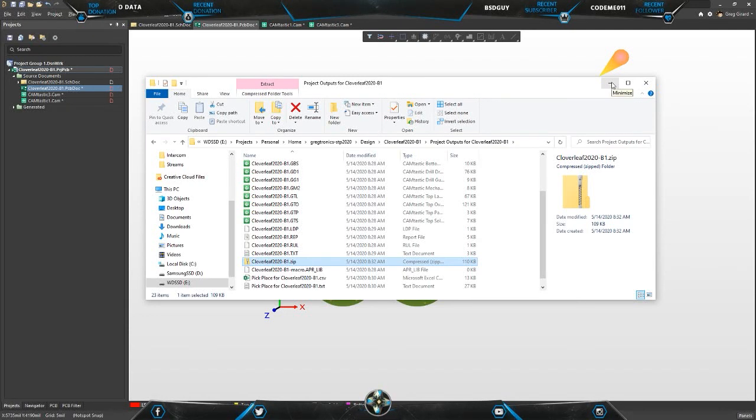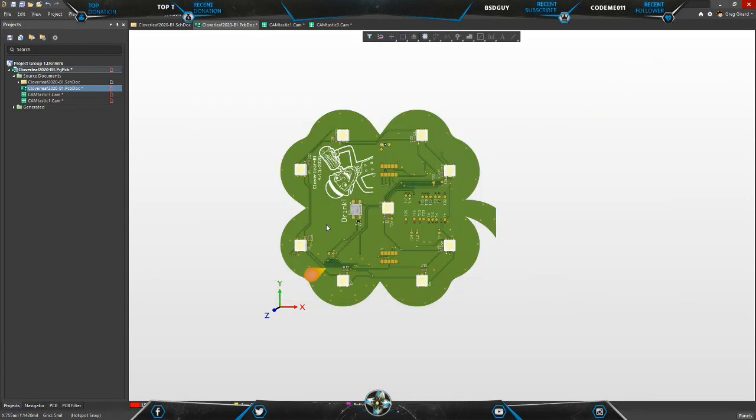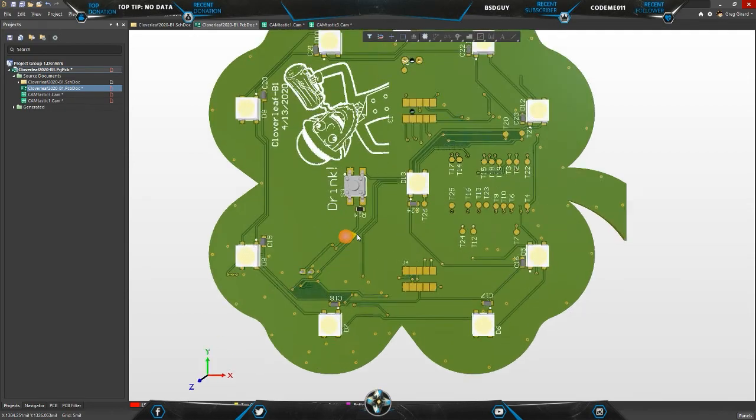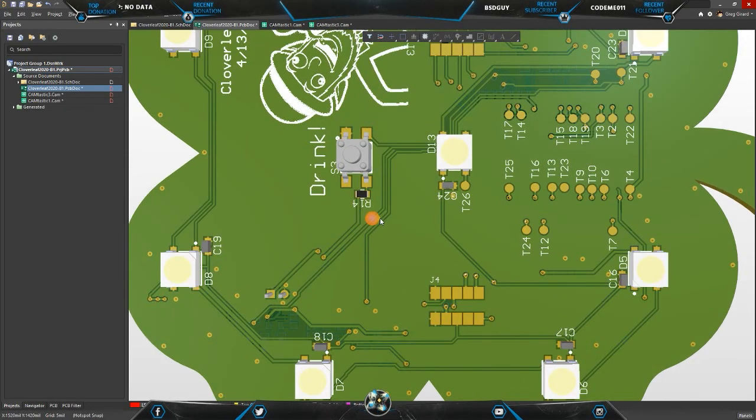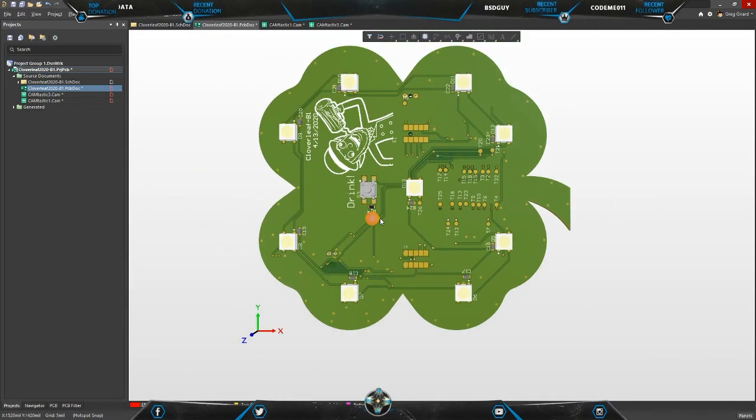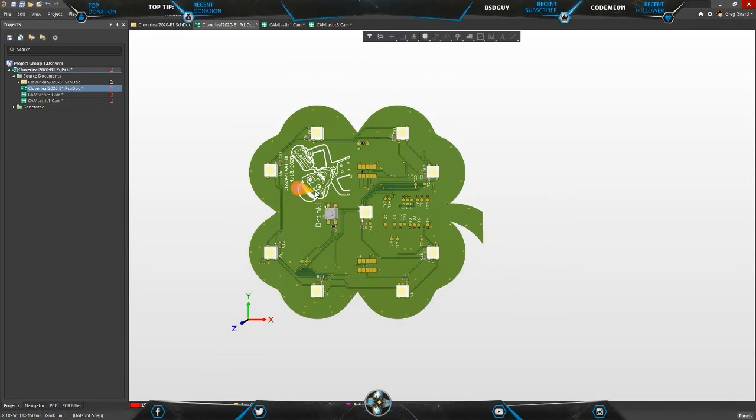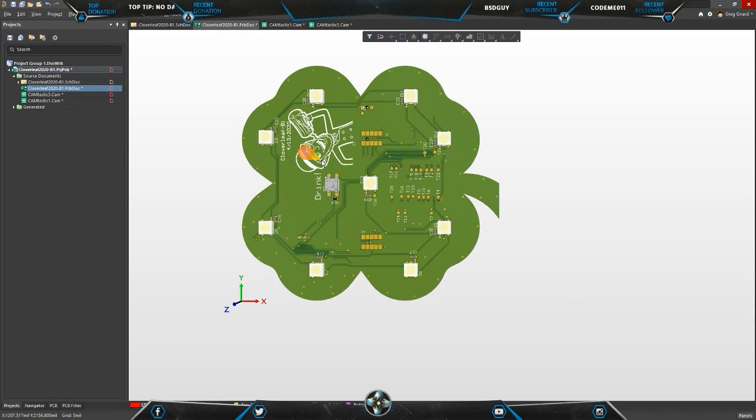They will need some other information. Usually they'll ask you basics such as your layer stack, your design rules of how you use your space and trace, finish type, those types of things. I'll cover those in a different video. This is just for kind of what files they need to get up and running.